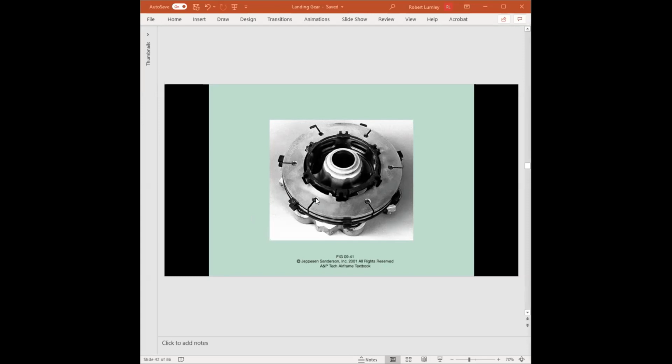It's to prevent warping of the disc, because the brake discs are going to get extremely hot. When metal gets hot, it tries to expand. If this was one solid piece, it would try to grow and expand, and it would actually warp. And so those slots are designed for the thermal expansion of that disc.